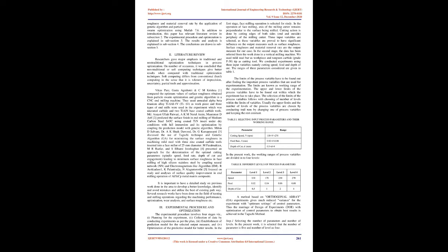Surface finish is the important output response in the production with respect to quantity and quality respectively. The purpose of the present work is to develop a mathematical model using genetic algorithm and particle swarm method for the optimization of machining parameters in face milling operation. Work speed, feed rate, and depth of cut have been chosen as predictors in order to predict surface roughness. Experiments have been conducted in a vertical milling machine based on design of experiment, 3 factors * 4 level orthogonal array design matrix. Surface roughness values are tested by Mitutoyo Surf Test SJ400 surface roughness tester for each experiment.